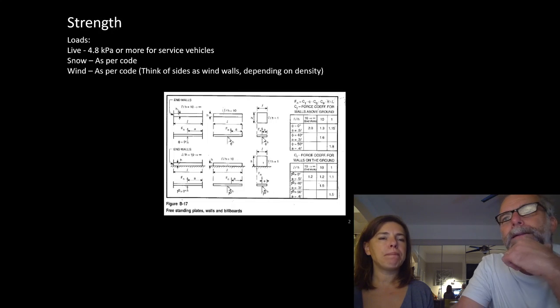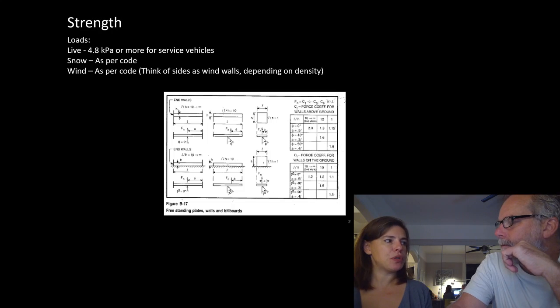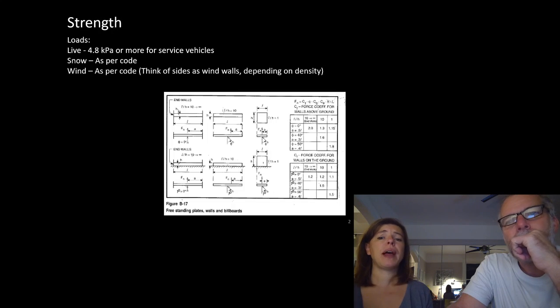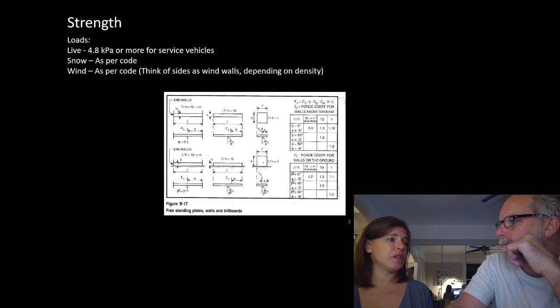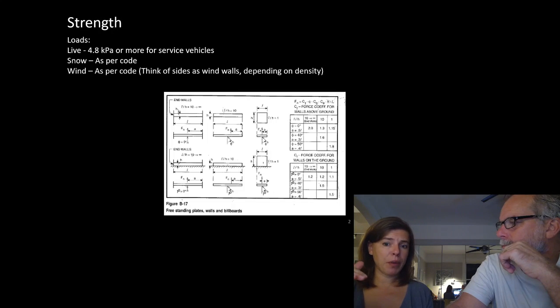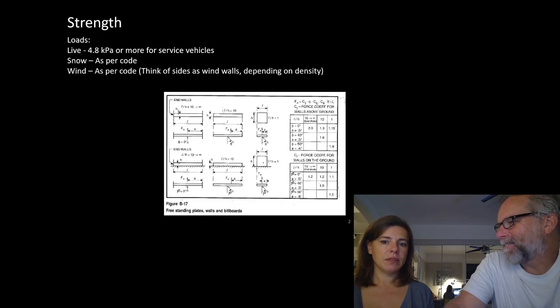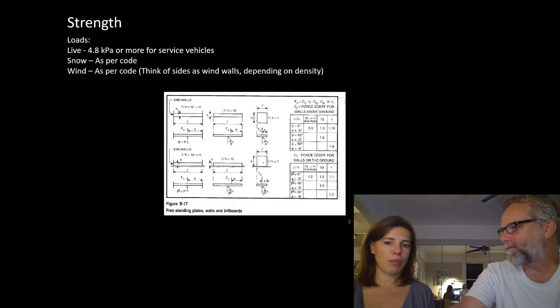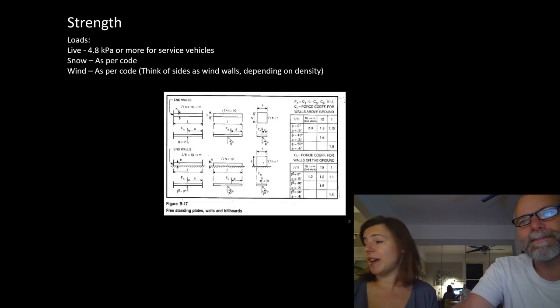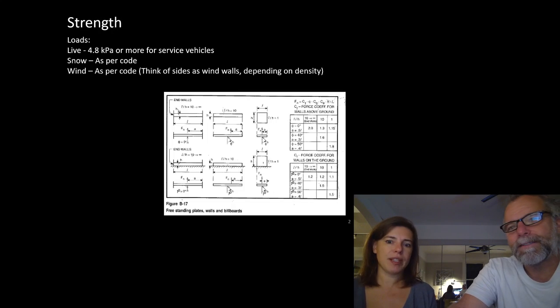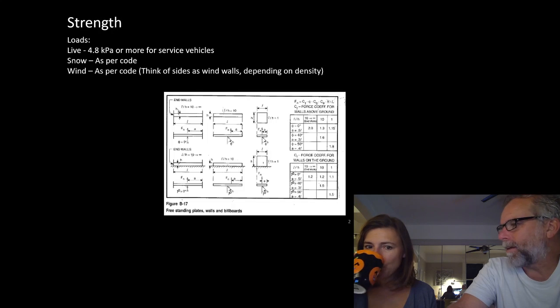It would have less impact than it might on some buildings, mostly because you have to consider it and go through the design, and they probably have a big diaphragm component, but it's probably not as demanding on a bridge as it would be on a building, I would imagine. I'm not saying it wouldn't be, yes. But in California, seismic governs every single element in the building. For a pedestrian bridge, it probably wouldn't. It would be something you definitely have to check. It might govern some of the members. Lighter weight and less stiff, right?